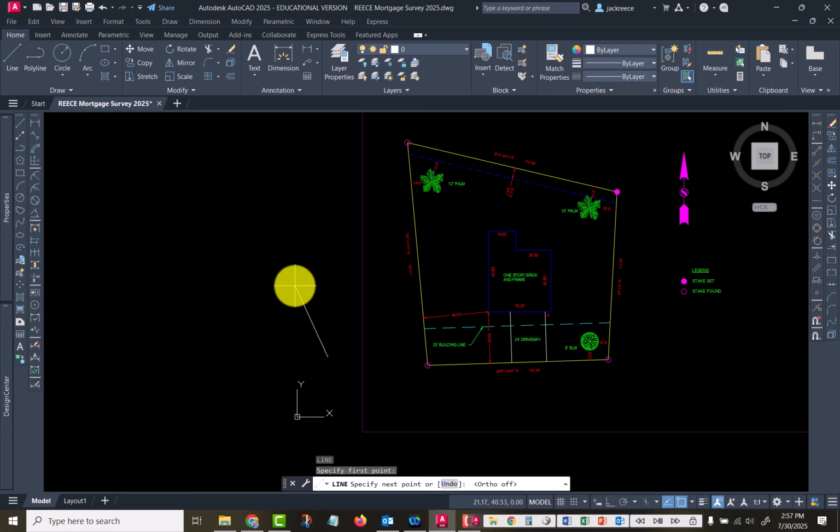Okay, and then it tells you to start it at an absolute coordinate and then give it a relative distance and bearing. So you're going to type it just like it shows in the textbook. So I'll go at 152.01 and then use the less than symbol on the keyboard. So it'll be shift comma, and that gives you an angle, and then you're going to type the angle in just as it's written in the book.